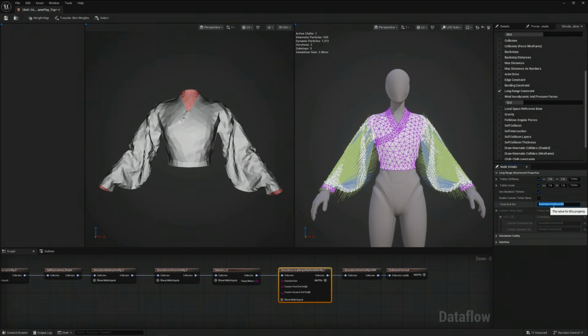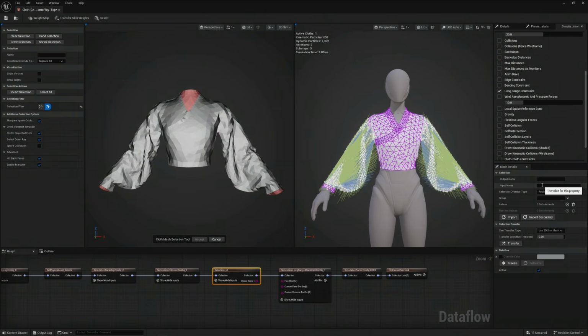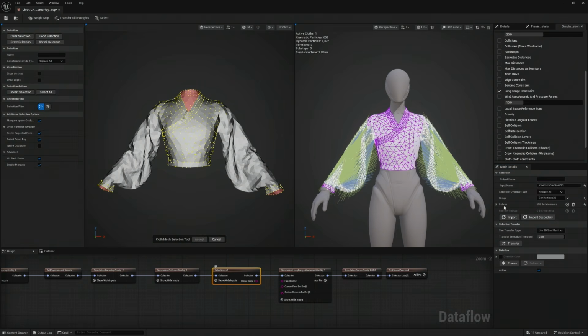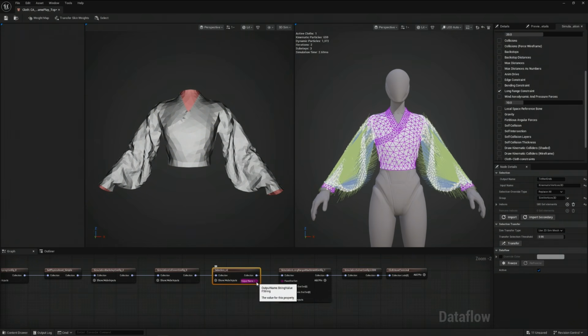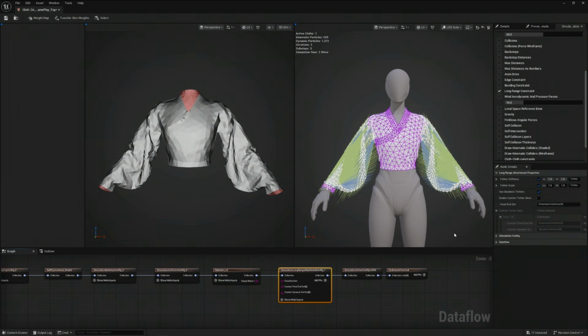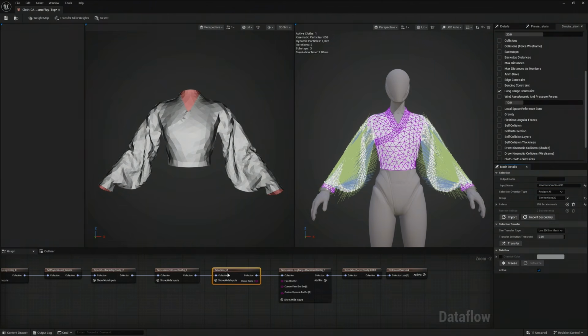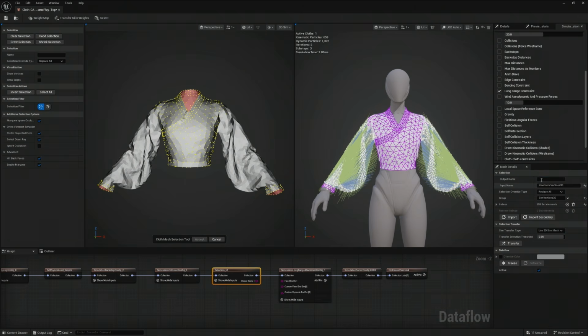As for the cloth I was testing, I also made a small adjustment to the tether ends. Because I made the cuff area kinematic, some vertices on the sleeve will connect to the cuff. But since gravity almost always pulls the sleeve downwards, connecting to the cuff is pretty much pointless. So I select and filter out those points on the cuff and only use points on the shoulder as tether ends, which makes the long-range attachment work more effectively.